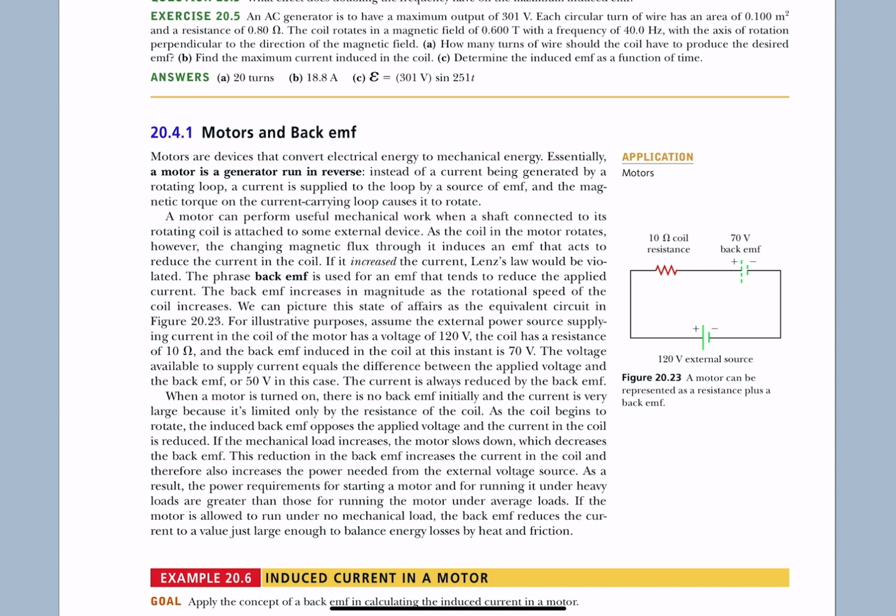But as soon as you have electricity going through wire, the moving charge going through the wire is going to create its own magnetic field. And that magnetic field that it creates, going around the wire, is actually going to push back and induce a bit of current opposing the movement of the current that's going through it in the first place. We call that a back EMF. It's a little bit of voltage that's reminding you it costs. It's going to cancel out a little bit of your voltage. That's called the back EMF.